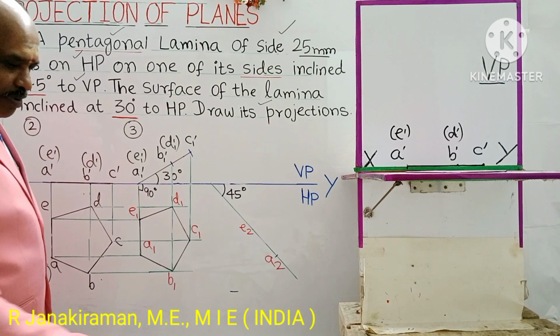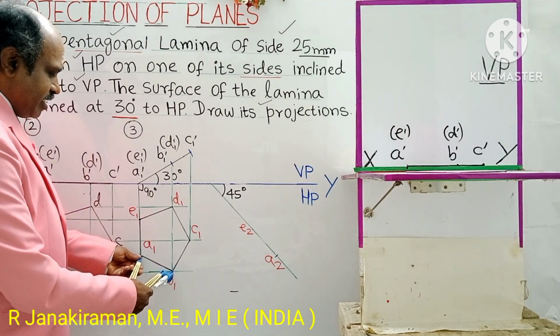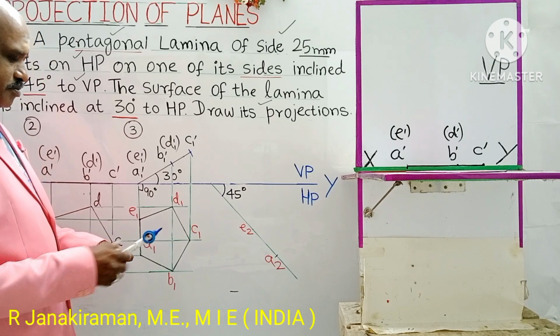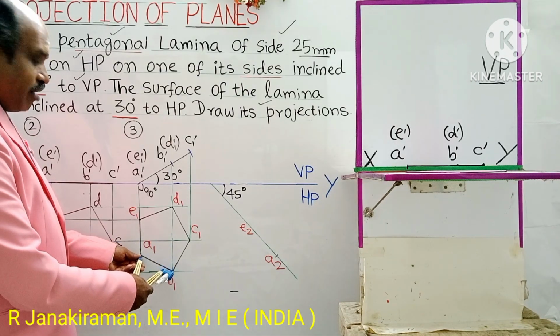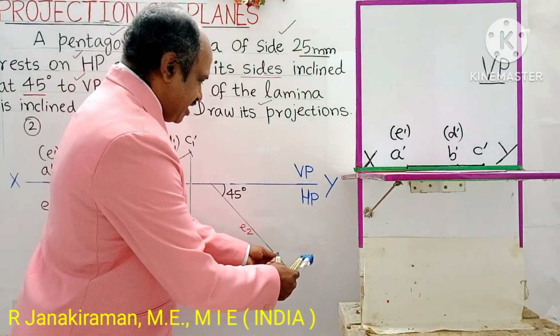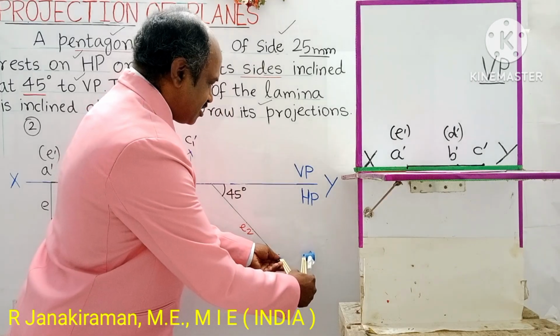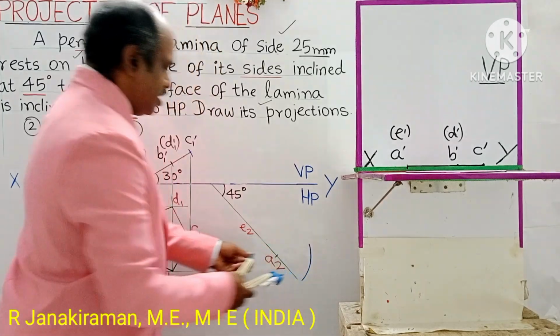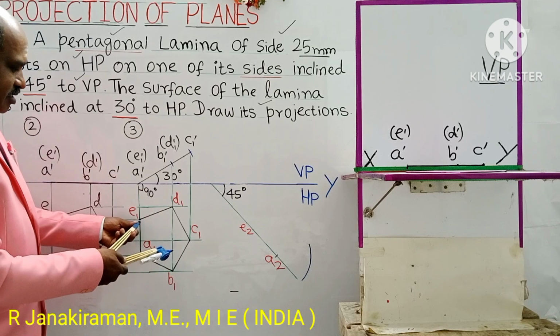Similarly, you have to copy paste the other points. Take the distance A1, B1. AB distance is taken in the compass with A as reference. Same as here, this is the A point. Draw an arc like this, a somewhat bigger arc. Similarly, take the E1, B1 distance in your compass.